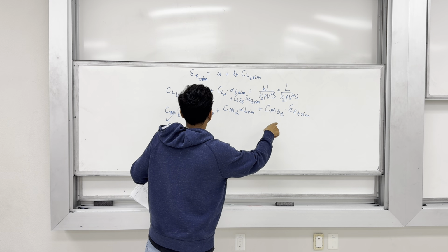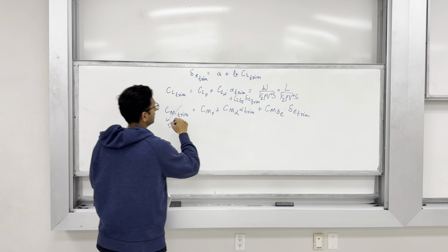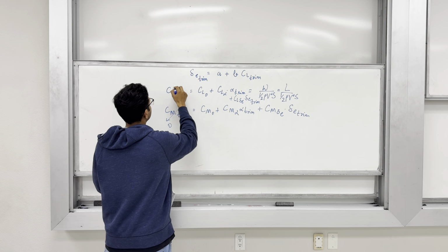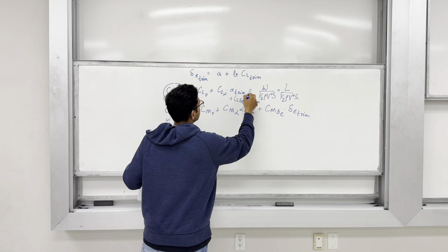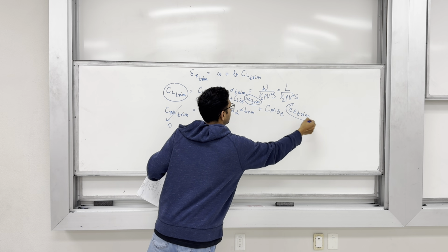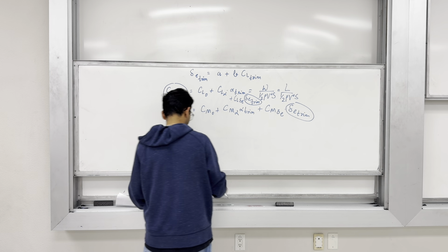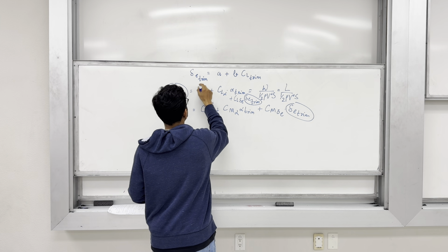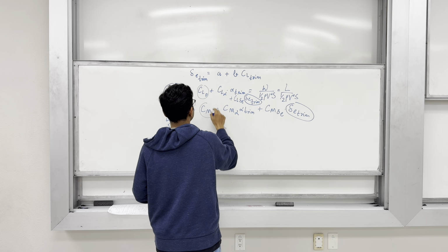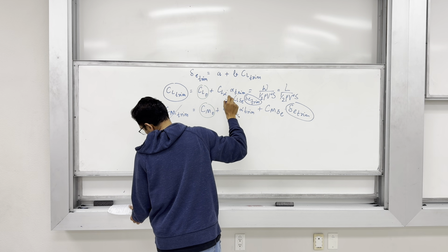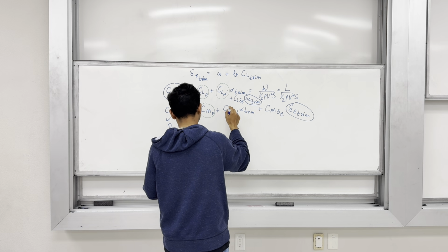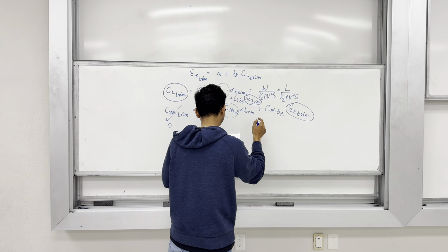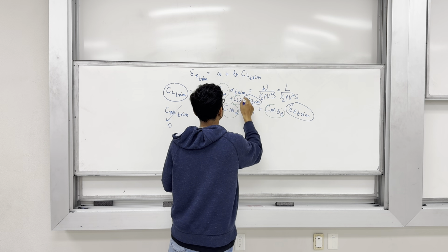So, finally, now I go and look at the data points, like what do I need? I need to express CL trim in terms of delta E trim, and let me check what I have and what I do not have. I know I can get CL naught from the question, I know I have CM naught data, I know I have capital CL, fine, no need of doing 2D 3D conversion. This is CM alpha, I have CM delta E is also given and CL delta E is also given.